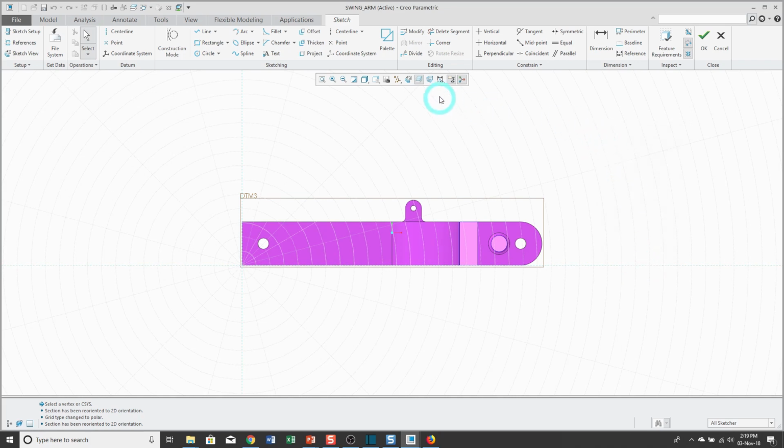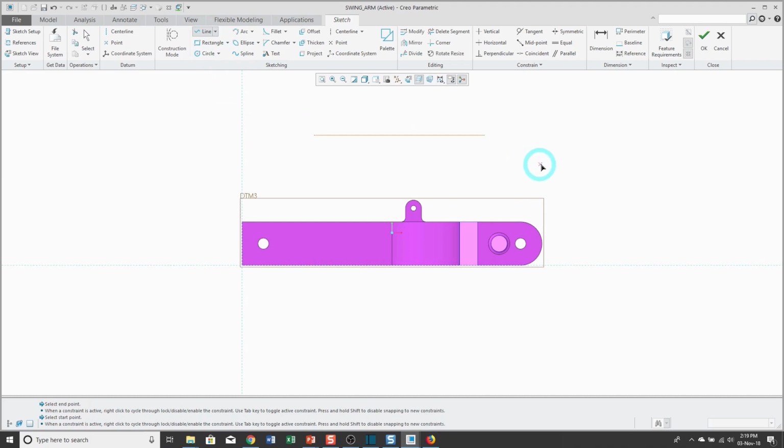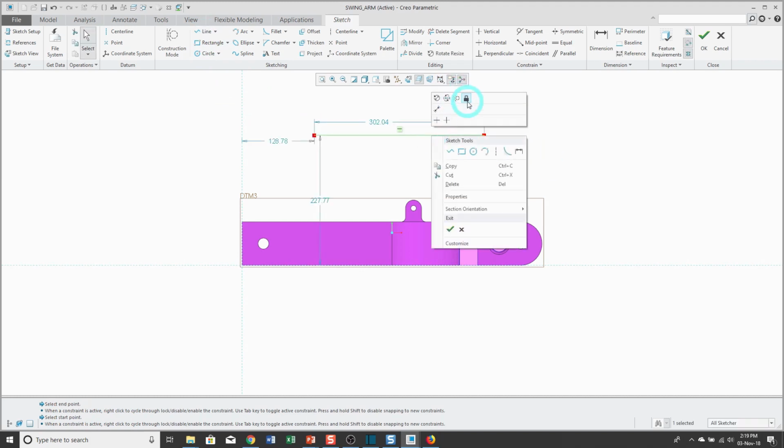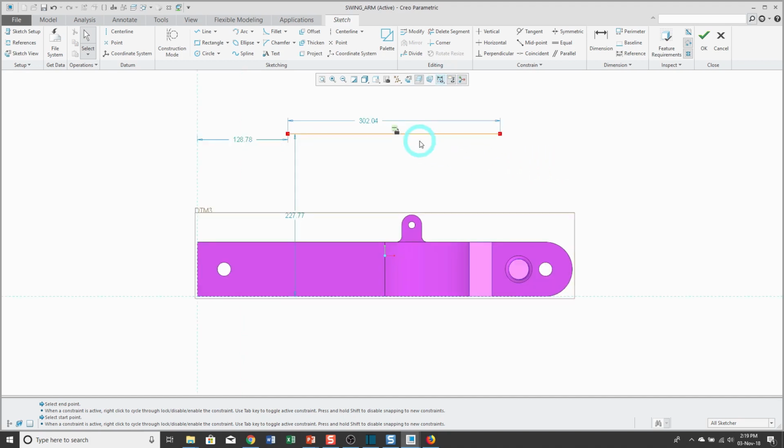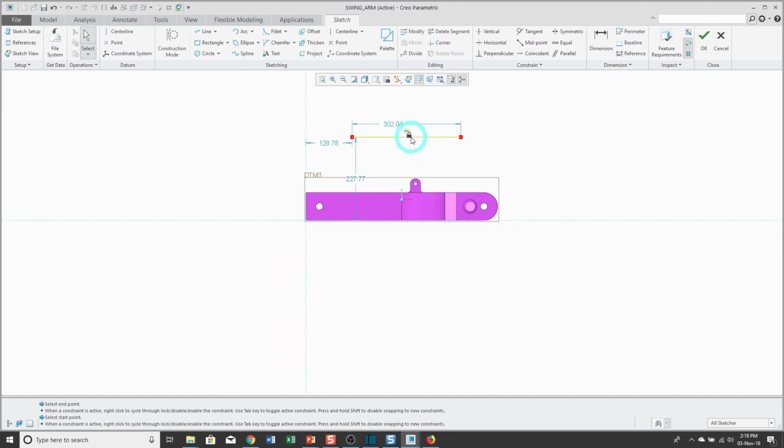All right, next up, let me turn off the display of my grid. There's also the ability to turn on the display of locks for locked geometry. For example, let's say that I sketch a line, and I can select that line and then lock it so that someone can't grab the vertices and dynamically drag it. When you have your lock display turned on, you can see that there is a little lock icon that shows up on the computer screen. So that's the In Graphics toolbar.